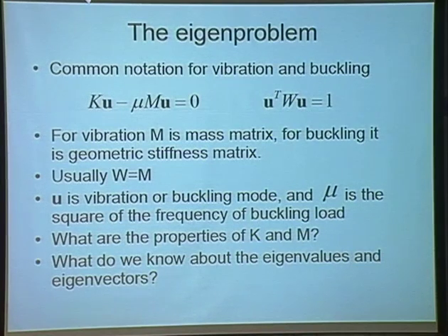And as a result of those properties, the geometric stiffness matrix, on the other hand, is not positive definite. And that reflects the fact that sometimes you can have a structure buckle under compressive load, and sometimes you can have the same structure buckle under tensile loads. That is, you can change the sense of the loads, and the structure will still buckle.